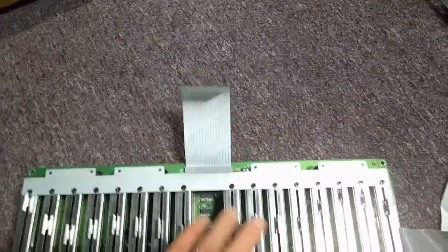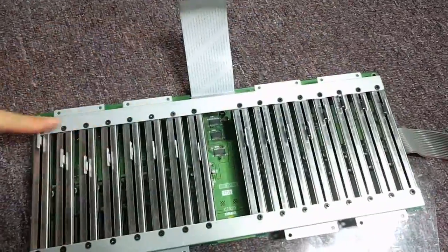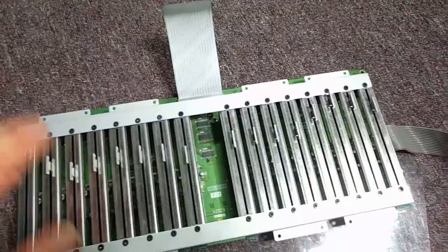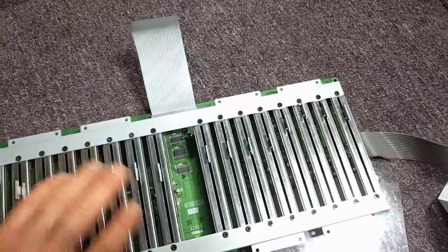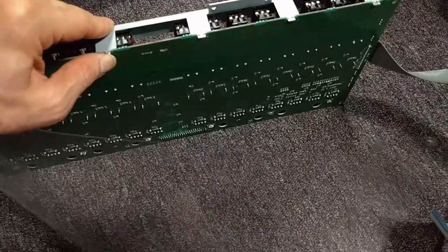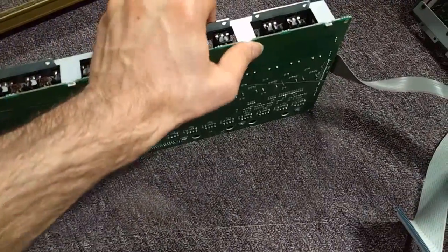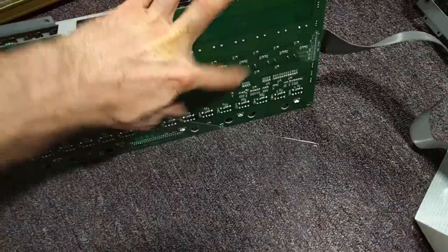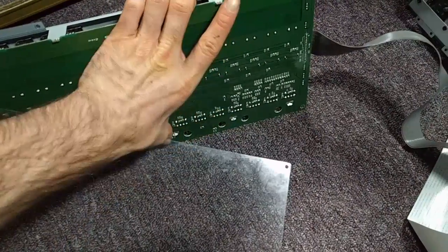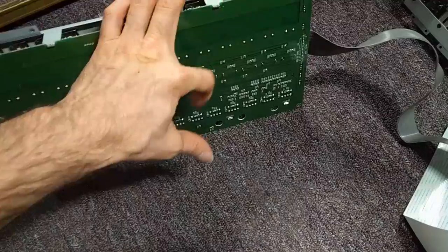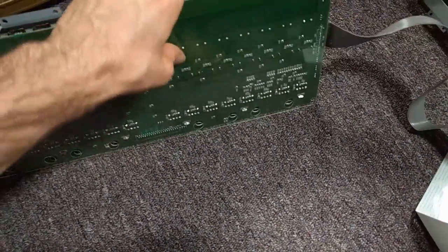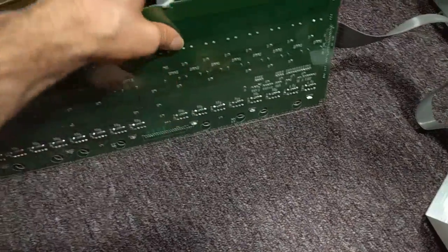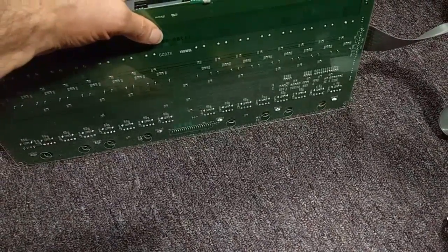The other thing to note is that you have to undo all of these screws after you've already done all of these screws to take it out of the main frame. Then once you're done with all that fun, you have to pry out each one of these tabs with some pliers, and you have to do the same down here, only these ones have solder applied to them, so you have to pry with a soldering iron and pliers at the same time. Fun stuff. You could try a desoldering pump, but it's such a massive heat sink that you're not going to have too much luck with that, I think. So that's what I ended up doing.